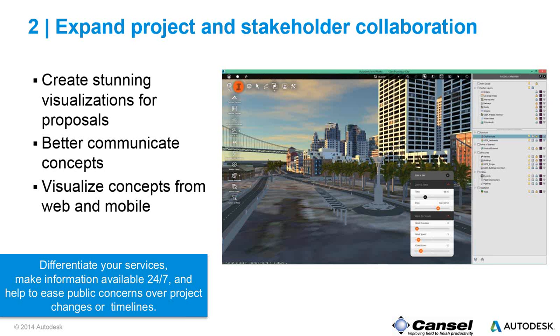So you create what's called a scenario. It uploads just that tiny piece of the model to the cloud, and your collaborator will be able to navigate your model. They can zoom around, they can pan, they can see your model completely without actually owning Infraworks 360. So you publish a scenario online and invite collaborators to view your model.